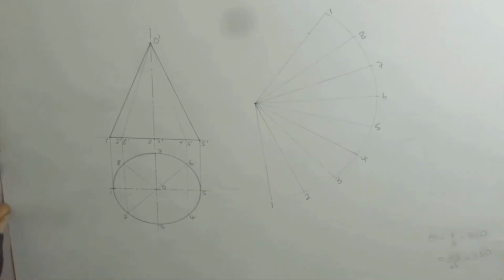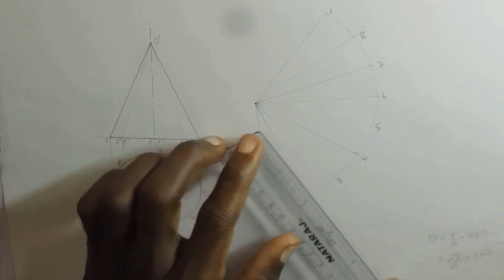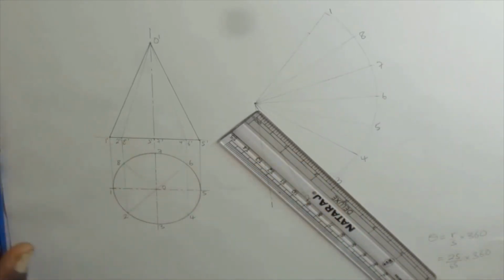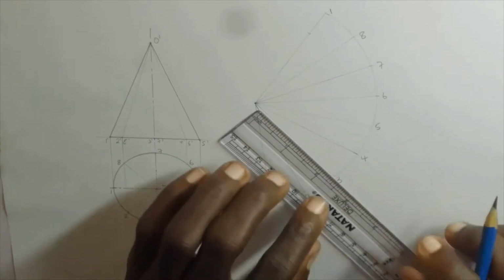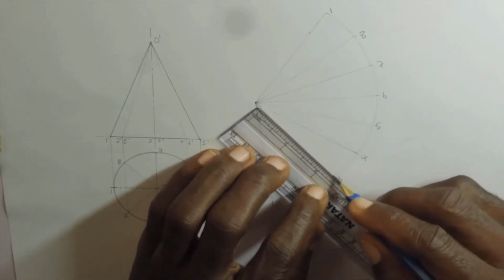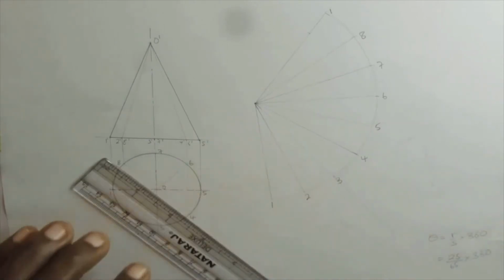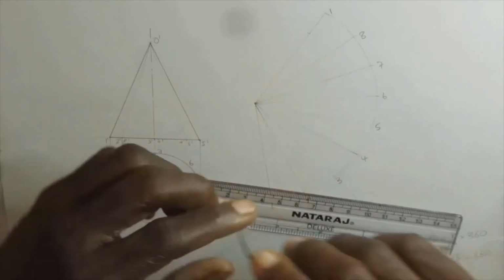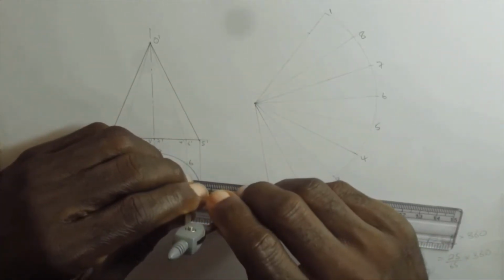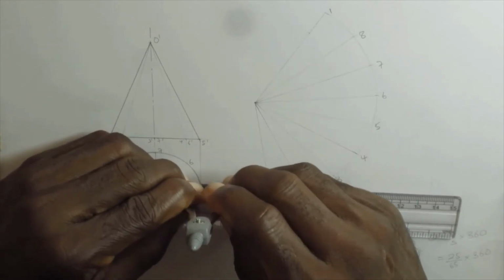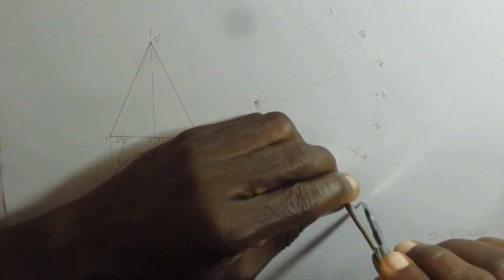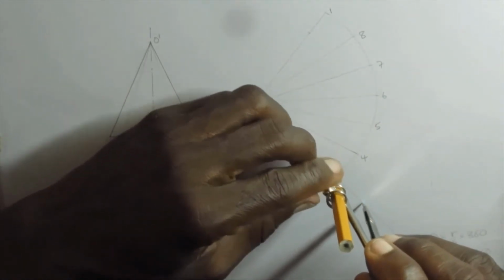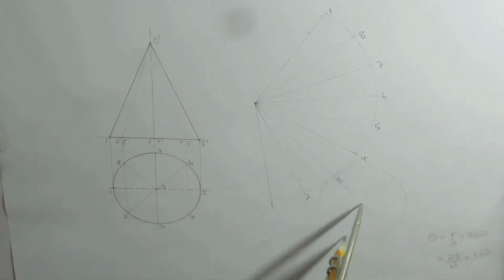Then we can decide that we want to add the base circle. So if the base is closed, then we need to have a circle at the base, and this circle should touch this arc at a single point. So in this case, if we want it to be at 3, then we draw a circle with radius 25 millimeters, touching this arc at point 3. So this is how we go about that. So we draw that base circle.